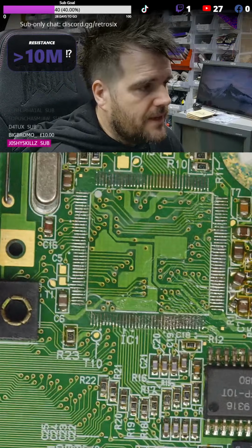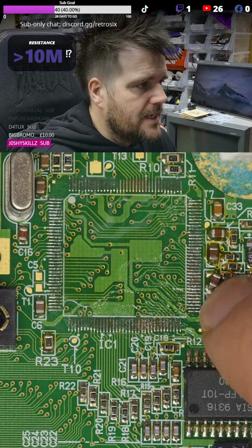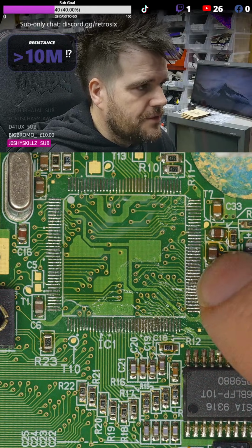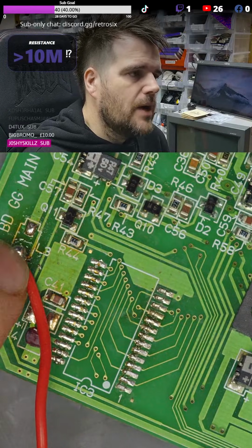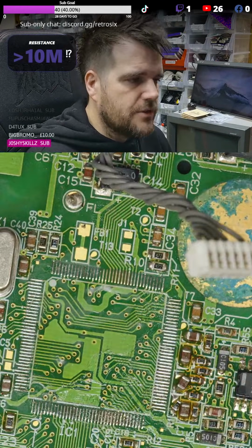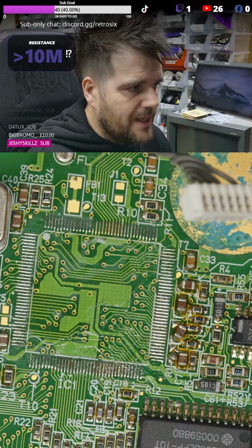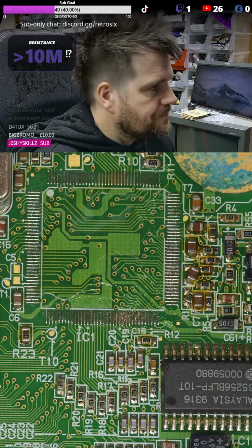Removing components, yeah, that's a good option if you suspect components and they're dead, like capacitors, which are semi-common to fail and short. You'd look at the schematic, find out where this rail is going, so we know it's the analog rail, and you could remove components that are on that rail until the short went away. That's a good method to find it. It's just a bit more long-winded.